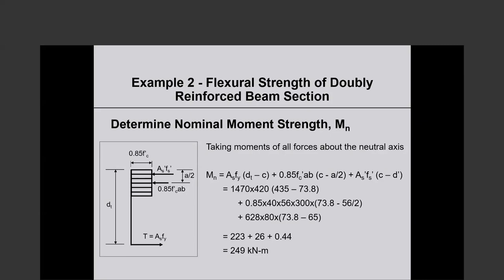For deflection check, there is a load combination which is dead load plus 0.5 times live load plus 0.7 times wind load. Is there any combination to check drift? And what should be done for drift?